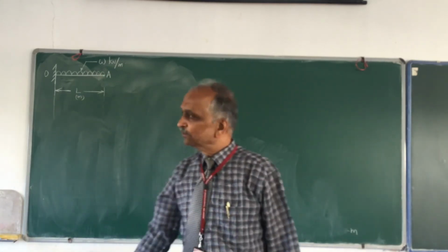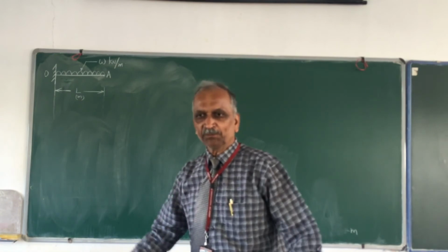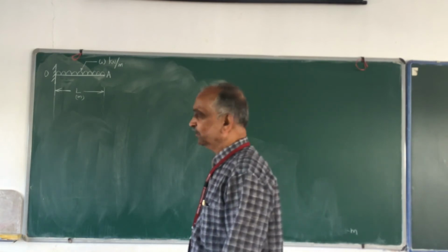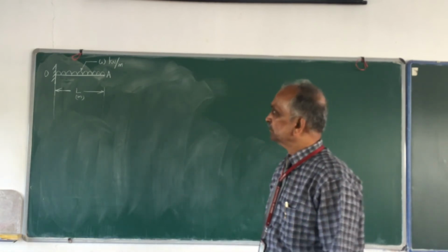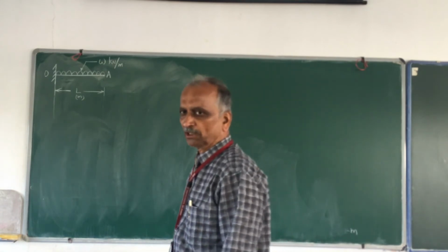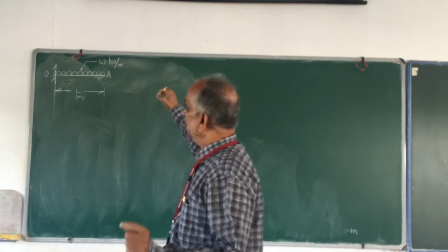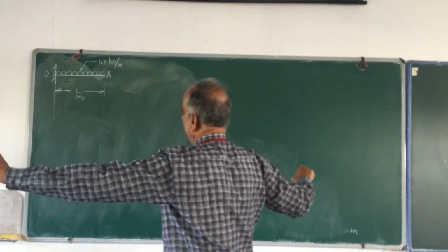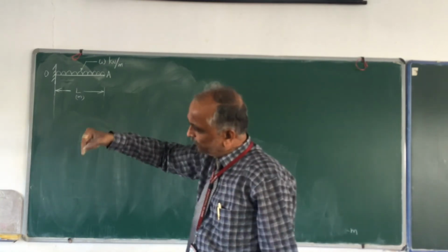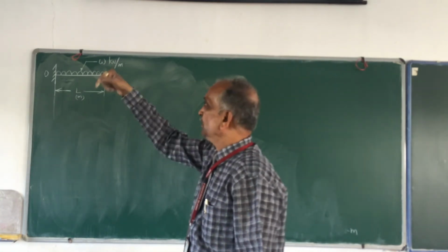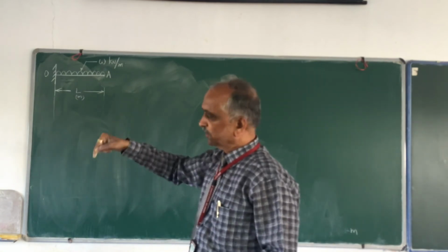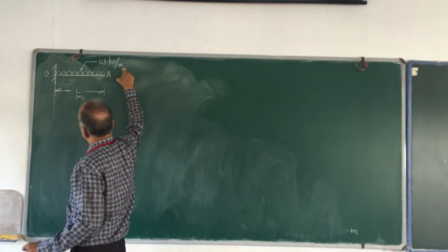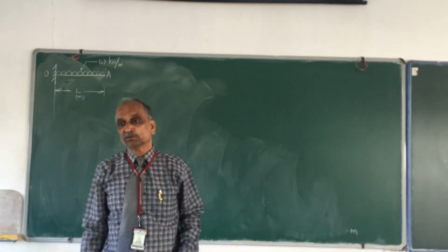Okay, so observe, quickly go through the given problem beam. Check what is the type of beam: the cantilever beam. What type of load is it subjected to? It is subjected to uniformly distributed load. I hope you understand. The load is not a point load. The load is not acting only at a point. It is spread over the entire length. So at every point, you have a load equal to W kilonewton throughout this length.